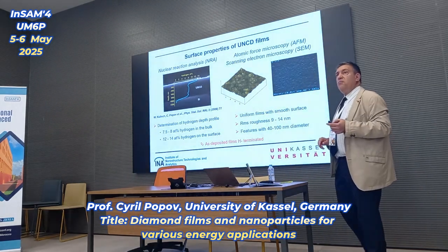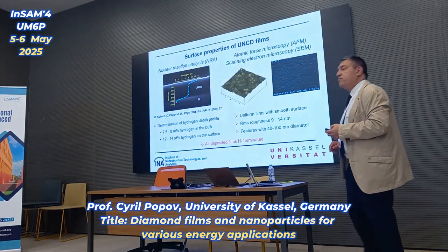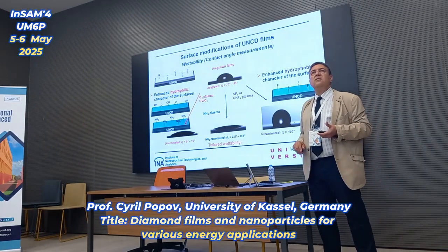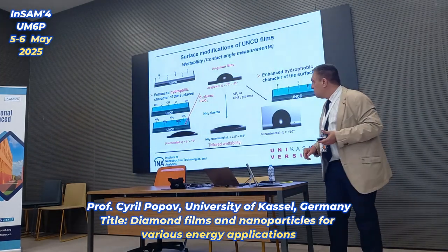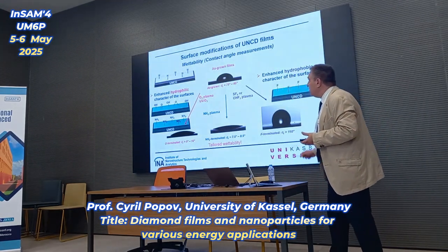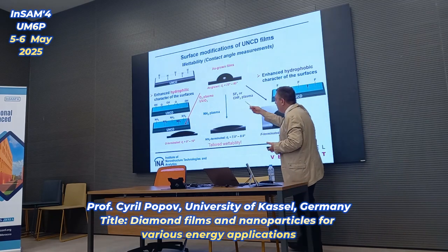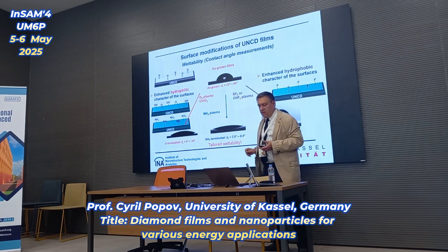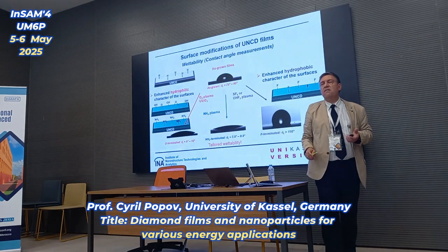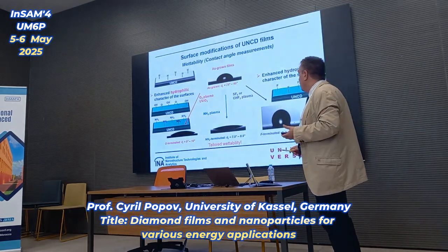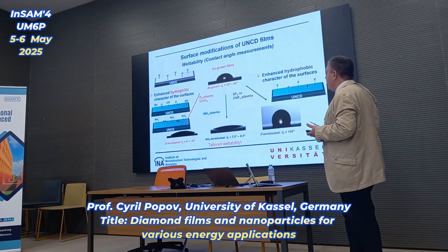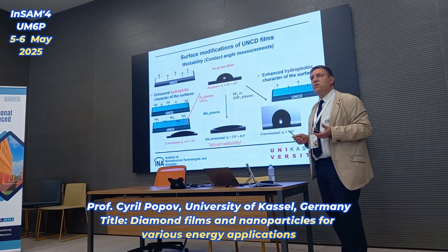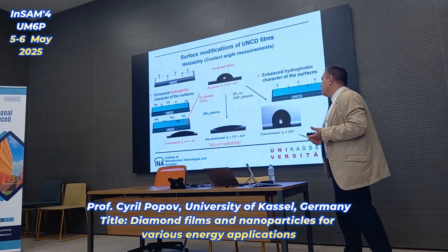The surface hydrogen makes the diamond surface stable, which is very good. However, sometimes we need some additional functionalities on the surface. So the hydrogen terminated surface, in this case UNCD, is hydrophobic, contact angle 75-85 degrees against deionized water. This stable surface can be changed applying highly energetic processes, either plasma or photochemical.